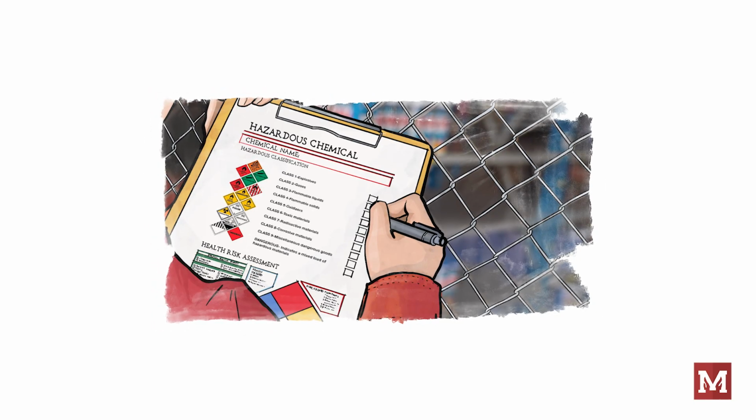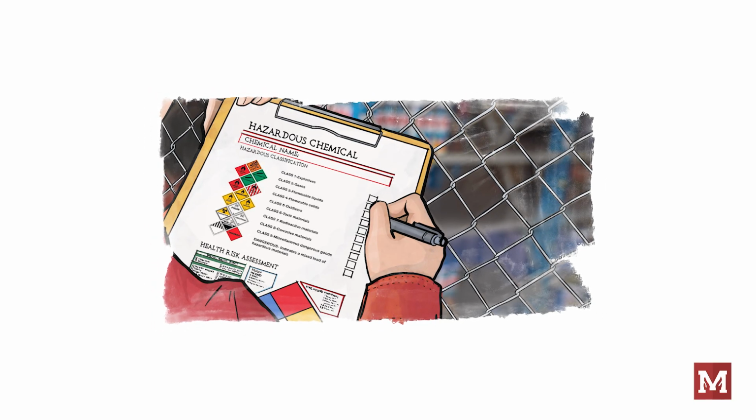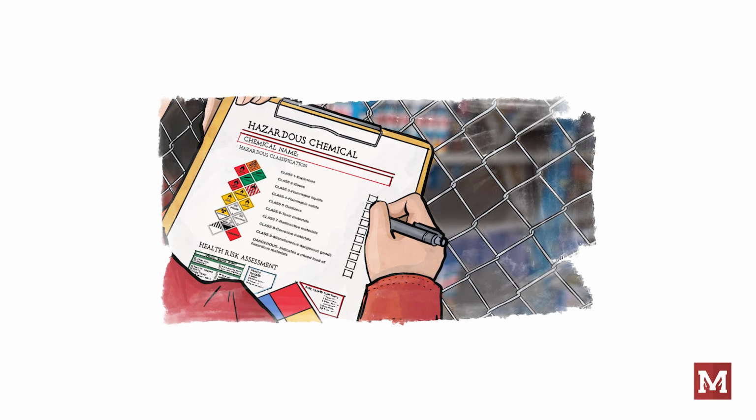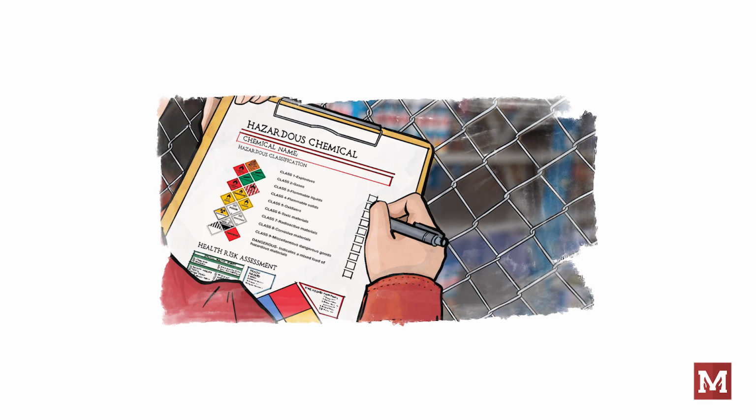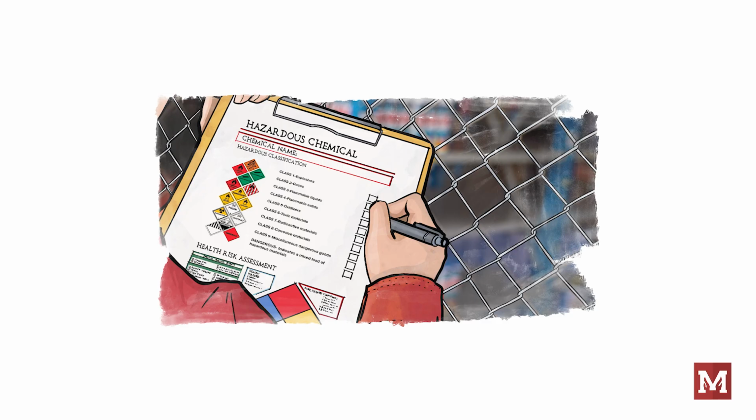From these definitions, health hazards are limited to corrosive, toxic, and highly toxic materials, while physical hazards are flammable, combustible liquids, gases, flammable solids. Note that the ordinary combustibles are not considered hazardous materials. Explosives, organic peroxides, oxidizers, cryogens, pyrophoric, unstable, and water-reactive materials.